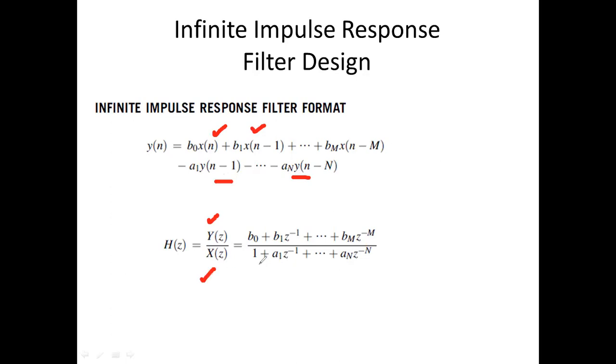You can see a peculiar transfer function with the denominator, the first value being 1. And unlike your FIR transfer function, you can see the denominator here is not 1, but there are values. So there are poles present in the transfer function. Okay. And all the coefficients related to the inputs go in the numerator, and the coefficients related to the y of n values, the output feedback, go into the denominator. Okay. So let us see an example.